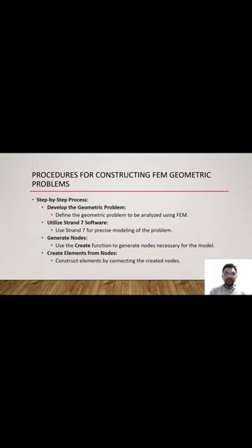Hi, my name is Satyashekhar Bhaskar Boruganti. I am from Group 14 and I will continue with the procedures for constructing FEM geometric problems. It is a step-by-step process where we have to develop a geometric problem using FEM with Strand7 software. We have to create nodes necessary for the model and create elements from nodes.